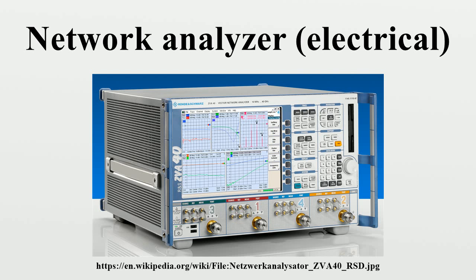It is impossible to make a perfect short circuit, as there will always be some inductance in the short. It is impossible to make a perfect open circuit, as there will always be some fringing capacitance. A modern network analyzer will have data stored about the devices in a calibration kit. For the open circuit, this will be some electrical delay and fringing capacitance, which will be frequency dependent.